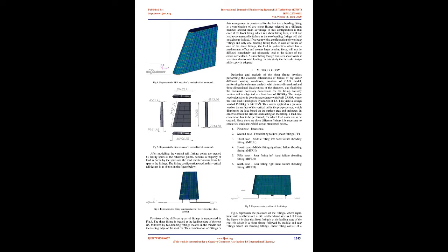The shear fitting is designed at the vertical tail and fuselage interface of an aircraft which is experiencing a suitable load. In this paper for the hand calculations, the ESDU 91008 method is followed, which is closer to the Air Force method. Here the shear fitting is designed for the critical load case. After identifying the critical loads by performing the load case correlation, then with the help of finite element method, analysis is carried out to see the behavior of the fitting and improvise its design.